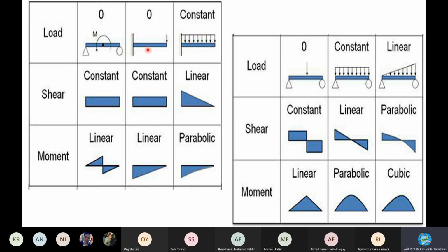When you go to a higher level, like year 4, year 3, theory of structures, I forgot the module name, a design or analysis paper, you have higher level analysis or frame analysis with all fixed ends. So you will have fixed end moments and the formulas are there. Either you derive or you remember those formulas to apply. Whenever there is a fixed end, it will impart a reactive moment, because it's fixed. Free, no moment, 0. It can move freely. Because it's fixed, the moment is arrested, and the member will react to this arrestment for any loading.